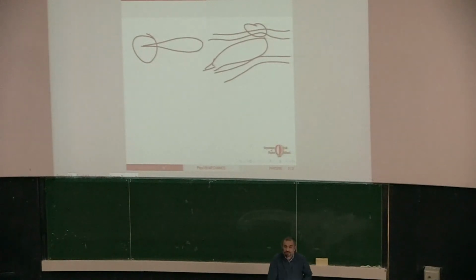Because we had already shown in the beginning of the last lecture that A1 times V1 is equal to A2 times V2. So if you squeeze a block of air or a liquid to go through a smaller area, you are increasing the velocity. If you are increasing the velocity, Bernoulli just tells us that you are decreasing the pressure. So on the top part, you are squeezing them, increasing the velocity, decreasing the pressure. Now this is conservation of energy, by the way. We are just applying the conservation of energy to an incompressible fluid.